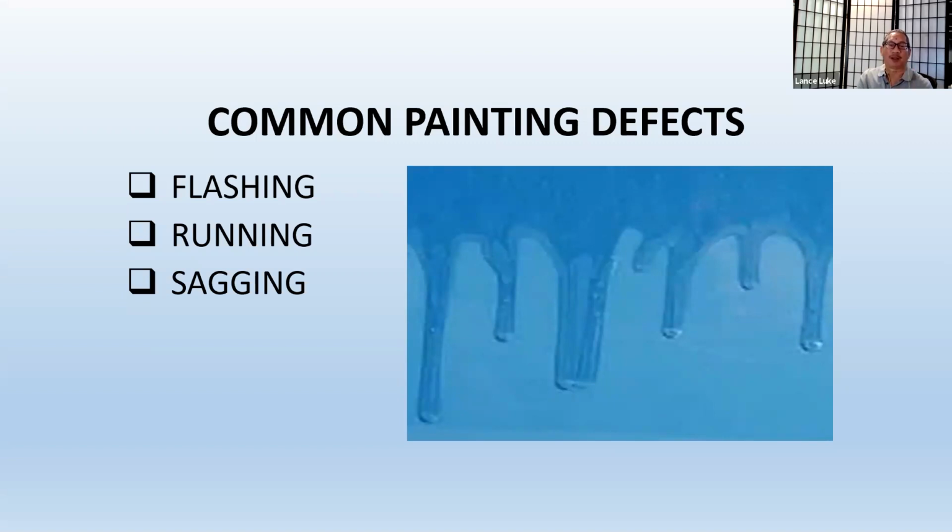Now, the sagging paint could be a similar situation, although in some cases, like let's say a high-rise building with concrete walls, the painting that you're doing now is probably the third time the building is painted, or maybe the fourth time. There's so much paint on the wall already that a new application, a fourth or fifth coat, would cause sagging. So the weight of that new paint would cause the old paint to start breaking off and sagging down.